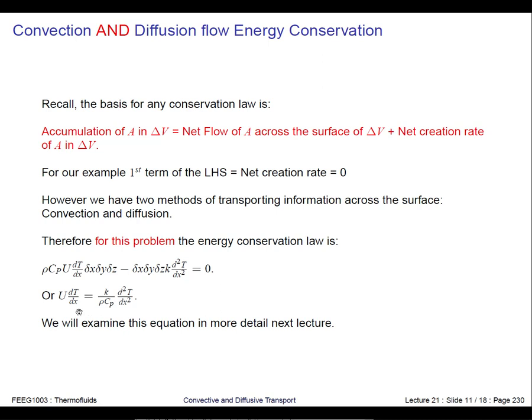Okay, so we've got our velocity and a first order derivative of temperature, and then we've got some material constants here and the second order derivative of temperature. So this is our convection diffusion equation, and we're going to see what happens when we change U and this constant here relative to each other. We get different temperature profiles. We want to understand what's going on.